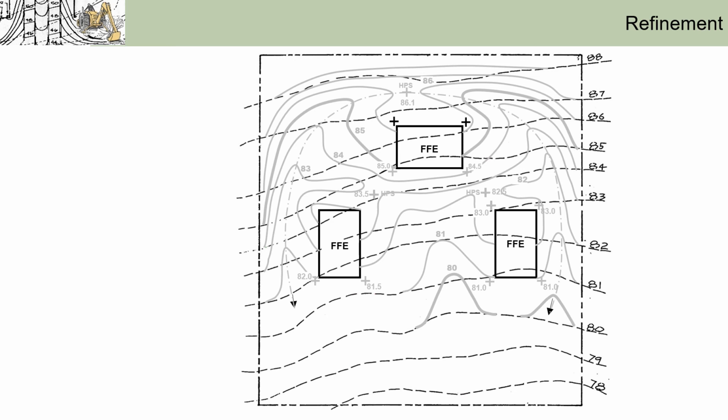If we look at the uphill portion here, both 87 and 88 had been moved. How can we make them stay closer to where they were? So what about moving the HPS and the center line of the large swale closer to the building? That way, the 86 and 87 contours can stay closer to the building, and the 88 does not need to be moved.